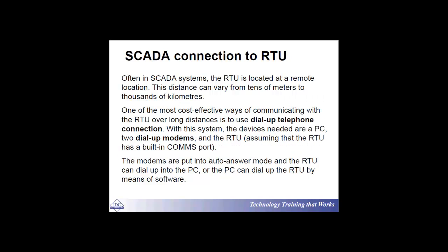So as I said, depending on what's available to you, whether telephone lines have already been established between the 2 points, or you have got a radio communication, you have got a mast, for example, you have got modems available, if there are any hills or mountains in between, if you have got satellite available, or if you have got fiber cables available or something, depending on the distance between the 2 points, your decision for communicating between all these RTUs could be different.